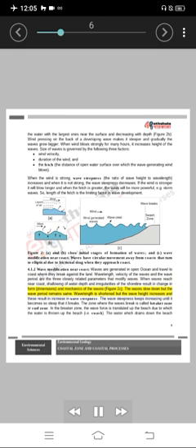The waves slow down but the wave period remains same. Wavelength is shortened but the wave height increases and these result in increase in wave steepness. The wave steepness keeps increasing until it becomes so steep that it breaks. The zone where the waves break is called breaker zone or surf zone.